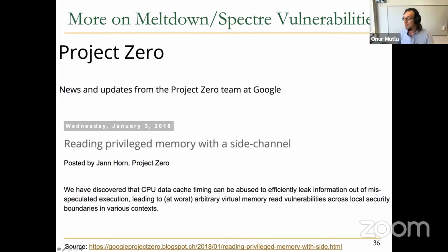Yesterday, for example, we discussed power management related attacks, right? Current management related attacks. If you're executing a power hungry instruction, you need to slow down some other process or some other thread or some other core. And this creates a side channel because you can see the timing difference when you execute with or without the power hungry instruction. And again, I would recommend attending the October 4th seminar by Javad, who talks about the current management mechanisms. In a sense, these are very similar, except Meltdown and Spectre are exploiting speculative execution, whereas the iChannels work that Javad will present is exploiting current management mechanisms. But these are all microarchitectural design choices that you make to improve performance or manage power, and they're creating side channels or covert channels inside the system. And if someone can actually be smart enough to exploit that covert channel, you can lose your private data.